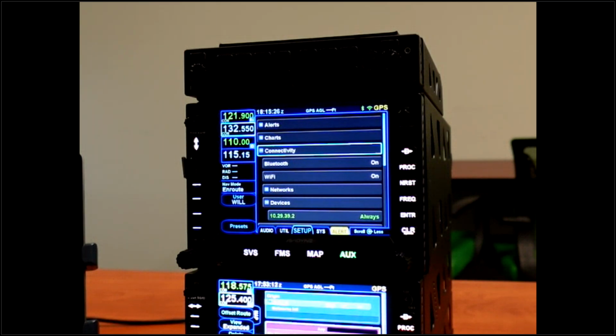Does the Dynon ADS-B In device work with the IFD 540? The IFD 540 does not, if it's through Wi-Fi. The reason for that is extended GDL90. I get a lot of questions on that in support. They use the extended GDL90 protocol, so you're not going to get wireless traffic and weather to the IFD. Are there plans to enhance IFD interfaces to allow Bluetooth devices, such as the Garmin GDLs, to work with IFDs? I'd say there's no plan at this time to do that.